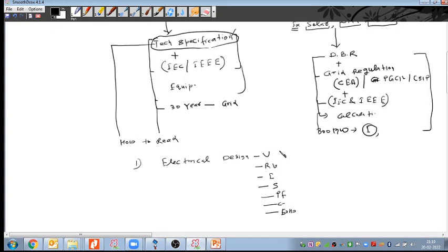So these are my electrical design criteria, and sometimes these criteria we also call system parameters. When we are making the drawings in the single line diagram, we need to mention all these things, and every equipment rating plate will have all these things on it also. This is the discussion that we had yesterday in the session, right? How to select the nominal voltage, rated voltage, impulse voltage, switching voltage, power frequency voltage, we discussed yesterday. Creepage we have not discussed yesterday.